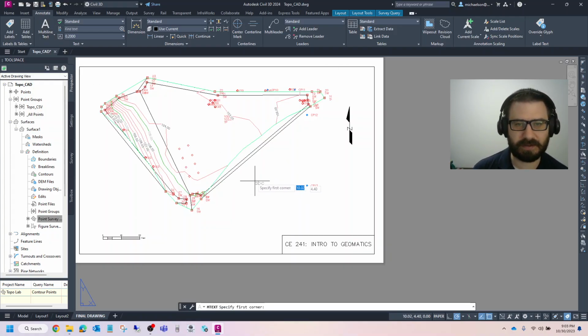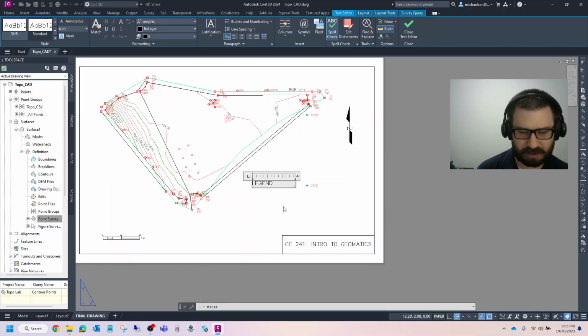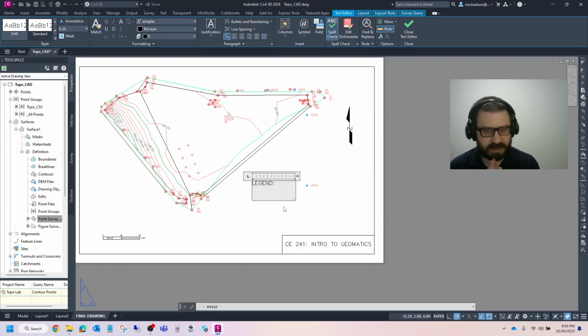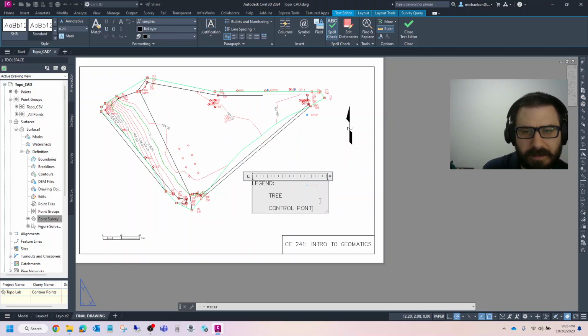Let's just create some text, right here, what have you. It's typical whenever you're doing a survey drawing that everything's in all caps. It's very rare that you don't put things in all caps. Okay, so what I'm going to do is, let's make that a little bigger.